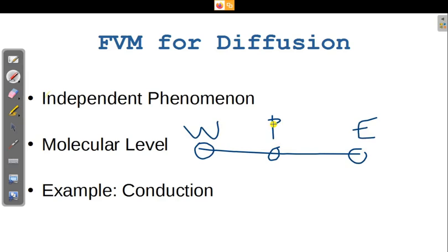And then what you will essentially be doing is treating the surface fluxes at the walls of this particular central element. The flux from the right side surface minus the flux from the left side surface will be exactly the net flux for the element considered in the center.